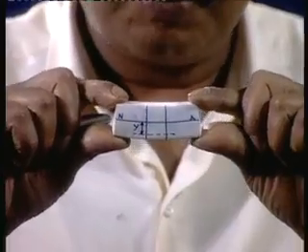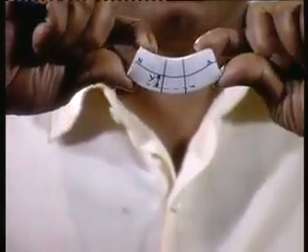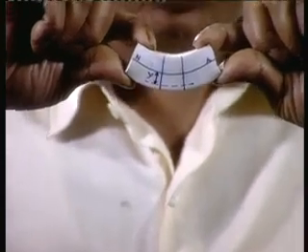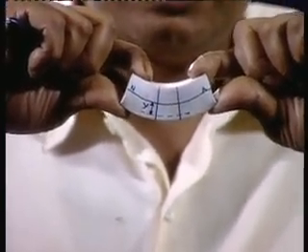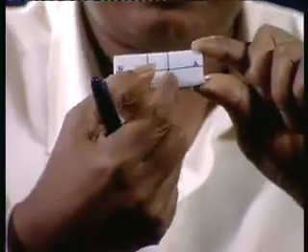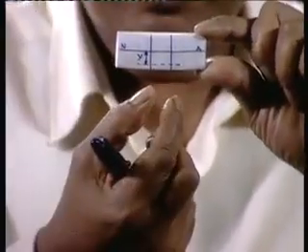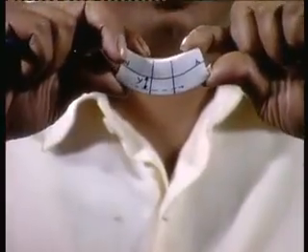If I apply a bending like that, you can see what we discussed earlier: the top fiber is under compression, so the length of this segment is compressed, and the segment at the bottom is extended, that means it is under tension.